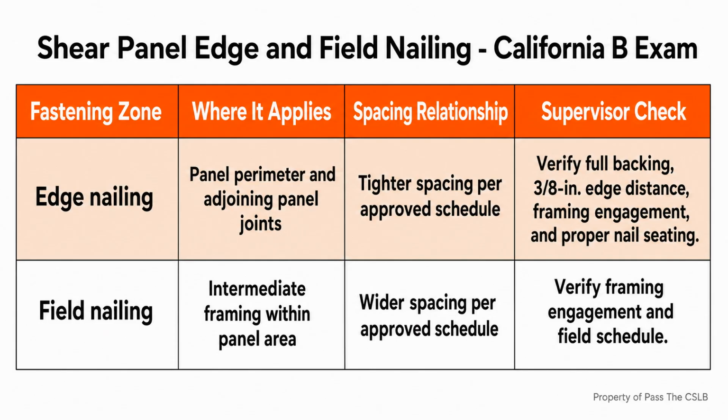Imagine a contractor who walks the exterior of a newly sheathed wall and sees a straight row of nail heads. From that side, the work looks clean. Then the contractor steps inside the frame building. Several nail shafts are shining in the stud bays because they missed the framing. A horizontal panel joint has no blocking behind it. Along another edge, a few nail heads are buried through the outer veneer. Those are 3 different defects, but they all break the same basic promise. The nail must connect usable panel material to usable framing.